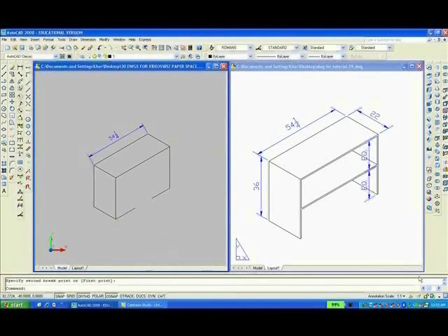I might add that all the material for this bookcase is hard-pressed wood, 3/4 inch thick. So what we'll want to do, say right away, is to offset the lines 3/4 of an inch to allow for the thickness of the material. So, O, enter. As I say, you can use decimal equivalents, it doesn't matter. 0.75. So I'll offset that line.